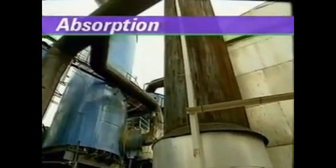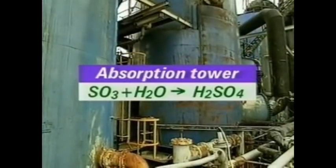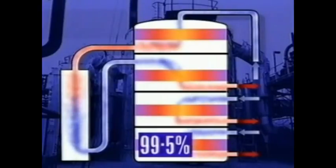After this catalyst bed, the gas stream is led into the bottom of an absorbing tower packed with ceramic material. The rising gas meets a stream of hot sulfuric acid that runs down the absorber. The sulfur trioxide reacts with the water in the acid to increase the concentration of the acid to about 99%. The gas from the top of the tower still contains some sulfur dioxide and oxygen and is fed back into the final bed of the converter, after which 99.5% of the original sulfur dioxide has changed to sulfur trioxide. Less than 0.5% of the original sulfur leaves the stack as sulfur dioxide.